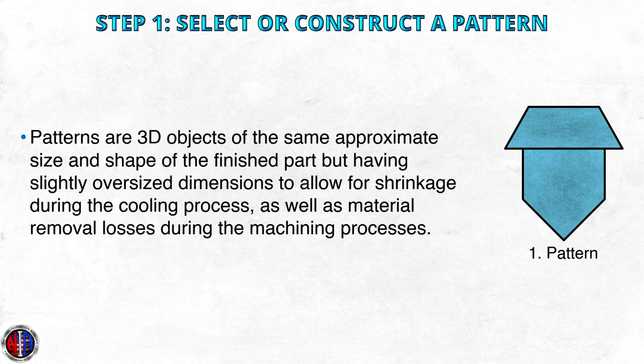Step 1. Select or construct a pattern. Patterns are 3D objects of the same approximate size and shape of the finished part, but having slightly oversized dimensions to allow for shrinkage during the cooling process, as well as material removal losses during the machining process.